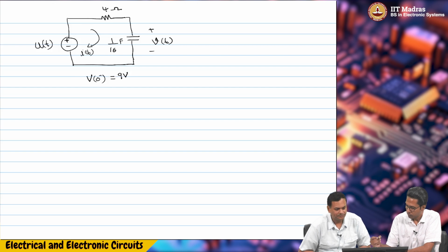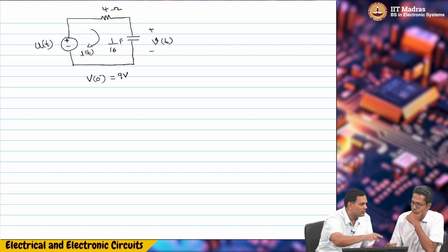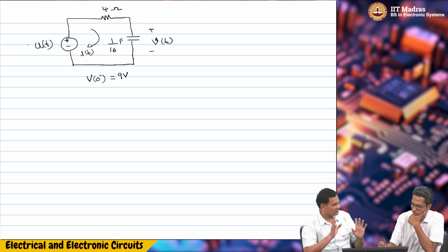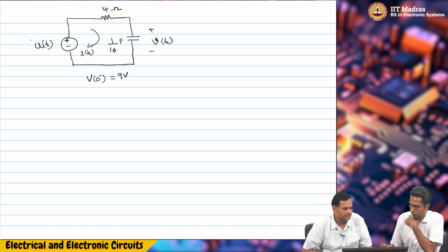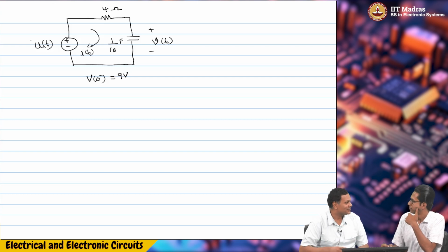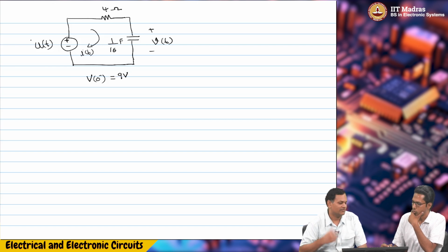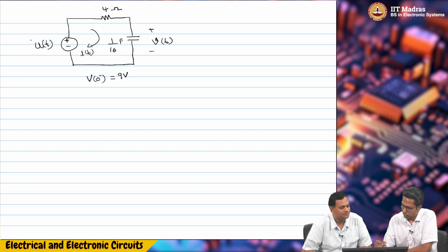So if you have a voltage source u of t, it is like a 1 volt voltage source in series with a switch that is thrown at t equal to 0. It is equivalent to that. We have done one RL example sometime, where we explicitly drew the switch, I think. It was similar, u of t. So first we'll write the time domain equation and then try. Yes, let's do that. So the time domain equation.